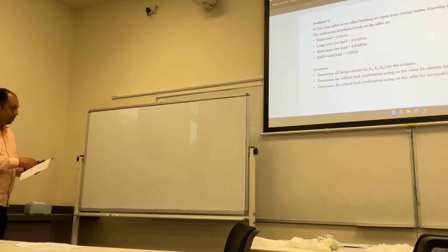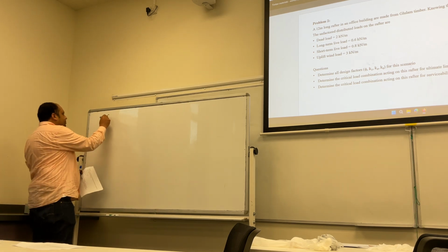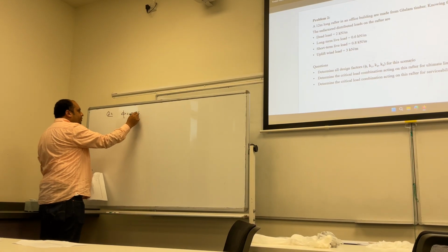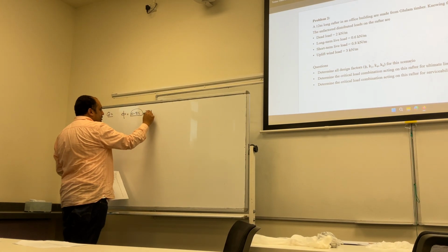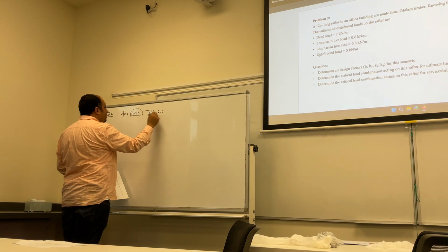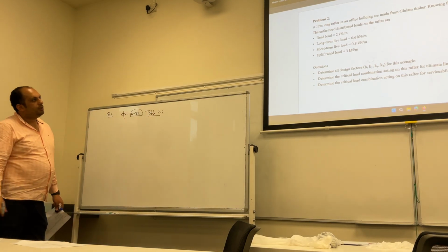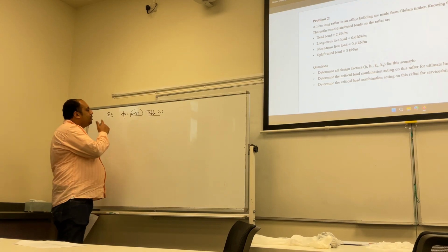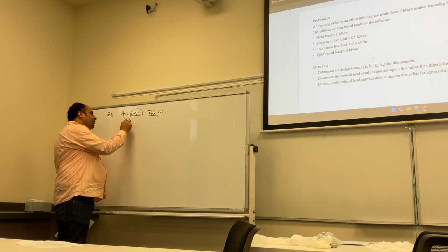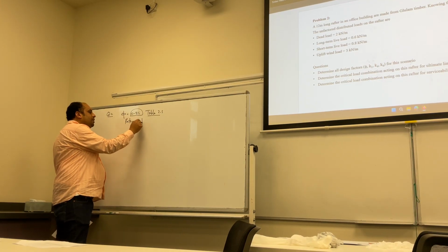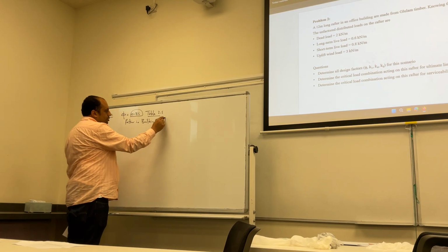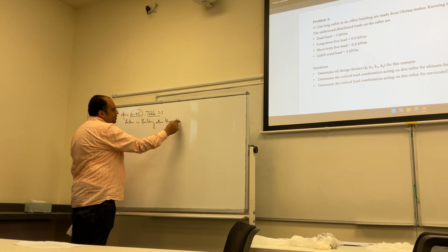0.85, category 2. So for K2, it is 0.85 from which table? Why? Because it's a primary structural member in a structure other than a house. So the rafter is laminated, a rafter in a building other than a house. And what is the type of the timber?